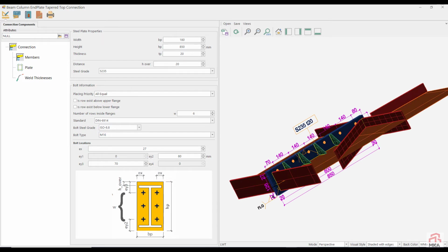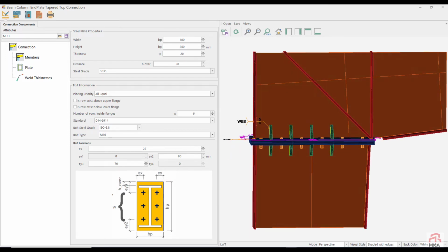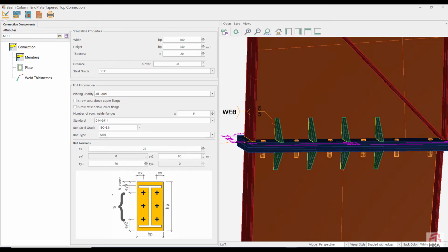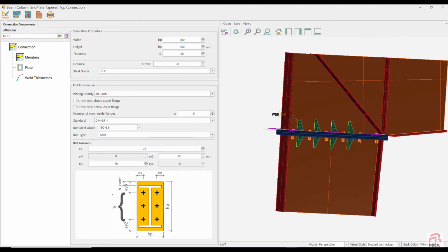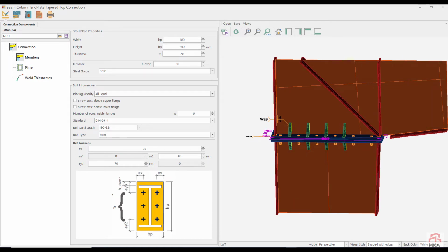Now it's sufficient. Is there an uncomfortable thickness or any problem in the connection? No, there isn't. We put the following connection plates in between, without considering them in the calculation. There is a stiffener plate for preventing panel buckling. It was meant to be done as a precaution. In order not to control the panel buckling calculation on the panel, we preferred to put the plate here automatically.